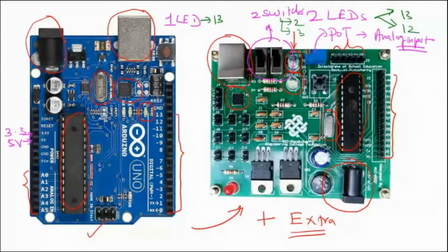These lines we use for powering external boards or external peripherals. Here we have 9 power connectors available. These 3 power connectors are used for providing plus 5 volts. These 3 power connectors are used for providing 3.3 volt. And a beautiful option here is we have 3 more lines which can provide plus 12 volts also. If you want to make use of this plus 12 volt, it is necessary that we power this board by using a 12 volt adapter.